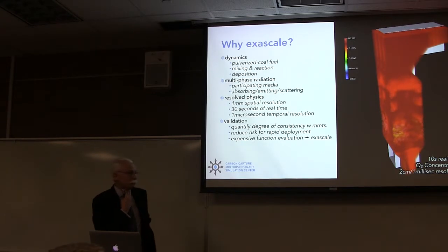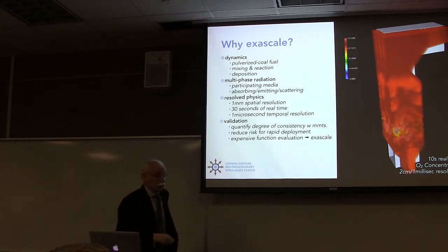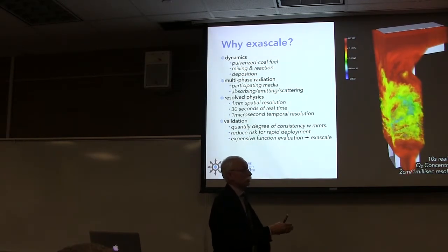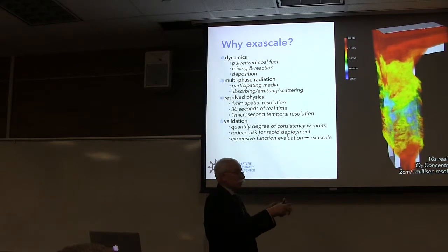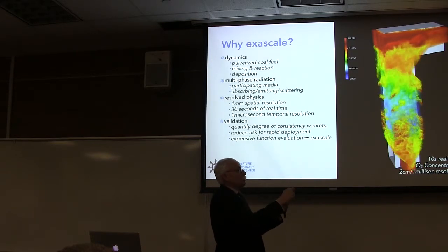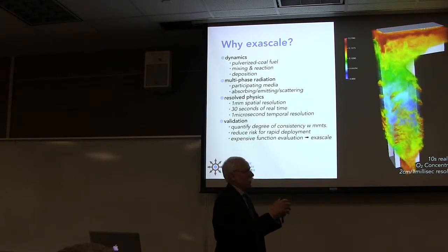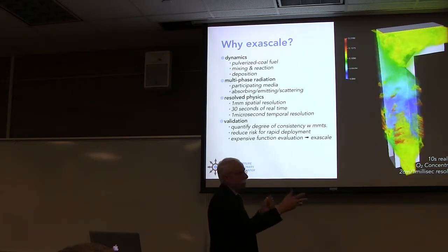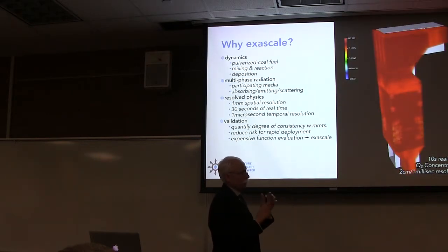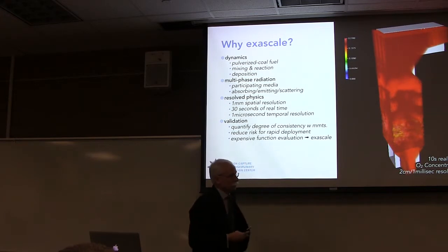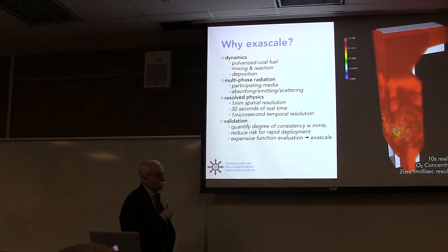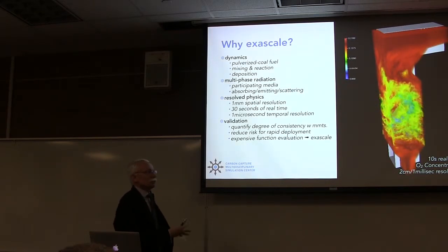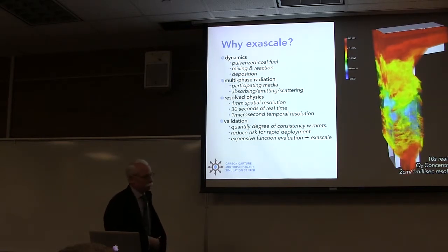Okay? Is that because pure oxygen would be too hot? That is correct, potentially. That's because pure oxygen is going to be a very different combustion system than existing systems. And most engineering systems are anxious to do incremental changes, not extreme changes. So there's a lot of work of pushing towards pure oxygen, but those kinds of systems are going to look very, very different than systems with diluents in them, with inerts in them. So this makes it look at least closer. It's going to be different already than air, but at least we've got systems that we can kind of understand that are somewhat like it.